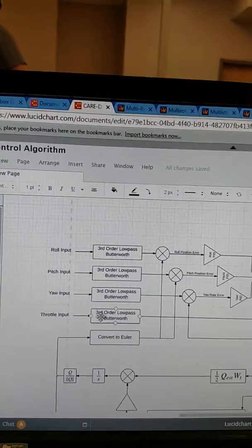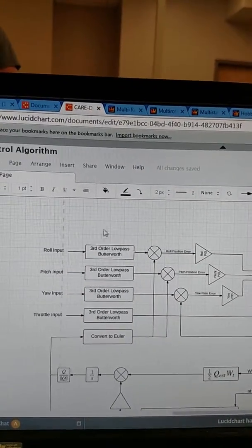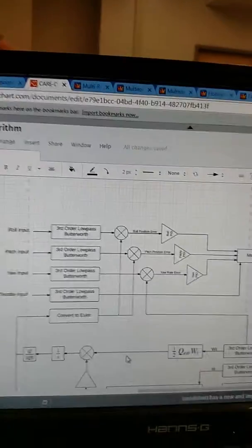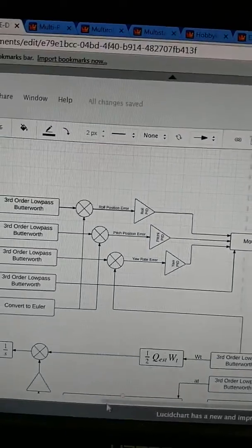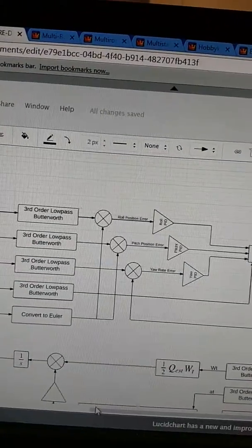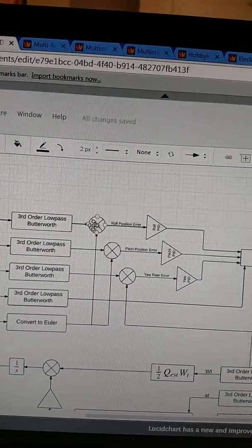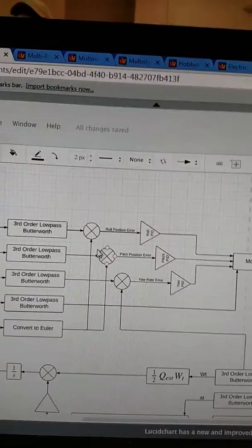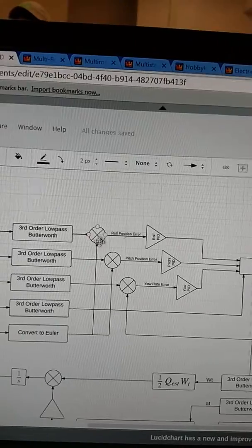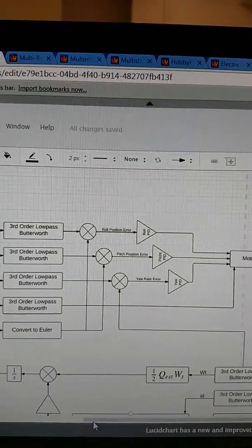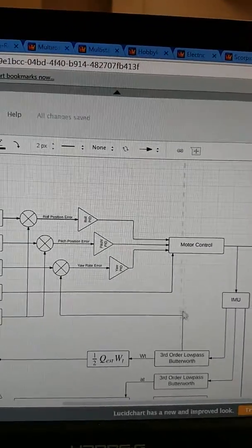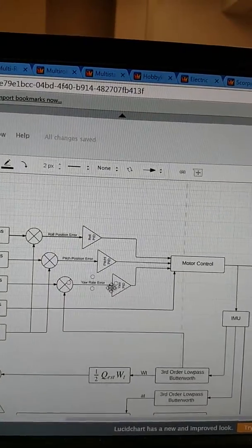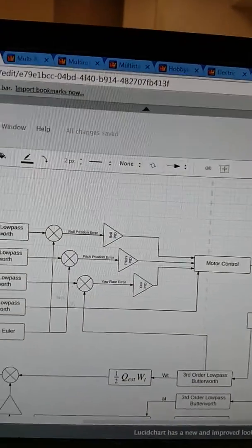It does add a little bit of filter delay, which, to be perfectly honest with you, the filter delay thrown in there feels right on the controller. So we're not too concerned. Then that data, roll and pitch, their PID control is control absolute orientation, basically position control. They're pulling from the feedback loop. The yaw is just pulling the raw gyroscope data. This is basically yaw rate is what it's controlling.